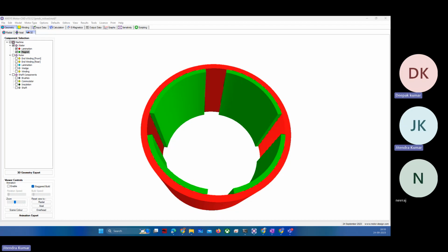The point of worry is that if you do not operate them below a certain temperature limit, the probability of those permanent magnets getting demagnetized permanently is very high. Once your permanent magnet is demagnetized, it will be very difficult to magnetize it again. To magnetize it again, you have to take it out from the stator core or motor or this machine. So your machine will be of no use.